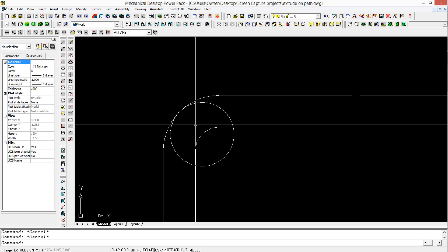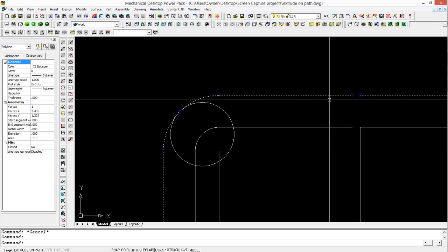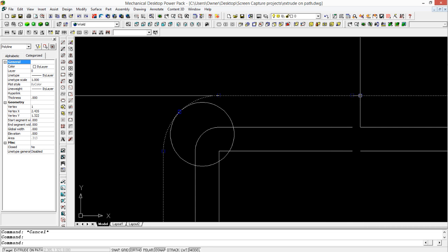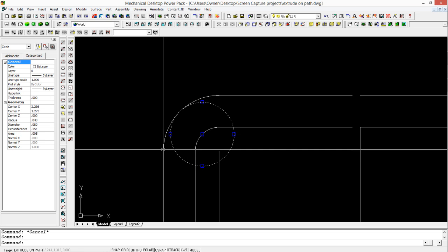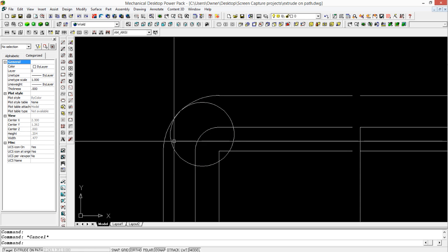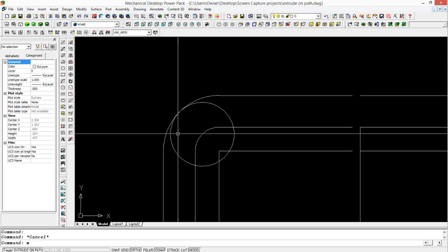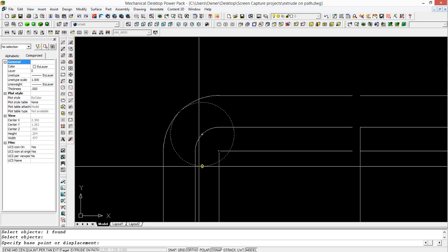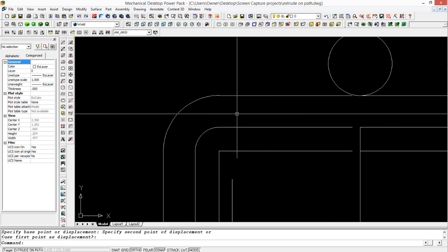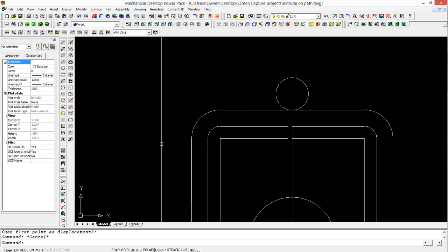So rule one is that you have to have an open polyline, because the sweep has to know where to begin and where to end. And rule two is that any radiuses along your sweep path have to be equal to or larger than the object you're trying to sweep. Let's see, let's get this and put it up here. And or extrude along the path.